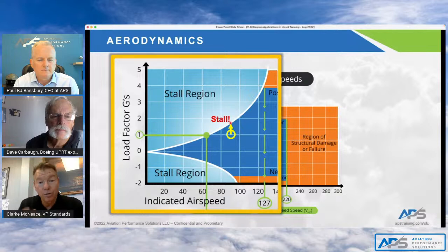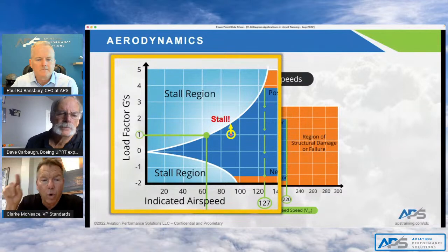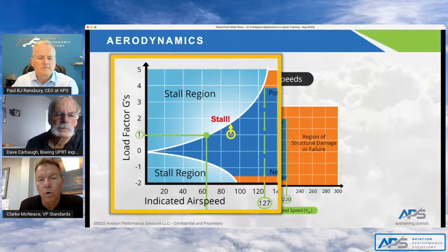Now, it's usually at this point that I like to say, does everybody understand why wake turbulence is so dangerous? Because visualize now being on approach in this airplane at 90 knots. And now you fly through a rolling vortex, some type of rolling vortex. And the airplane does an uncommanded roll to a 60-degree bank angle that you can't stop. Now, once that airplane gets to that 60-degree bank angle, where do you think the nose of the airplane is going to want to go? Yeah, it's going to want to go down.